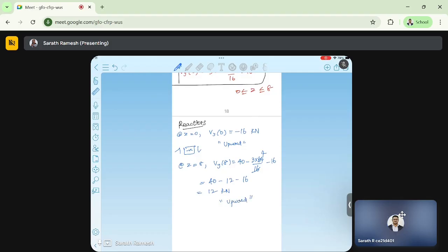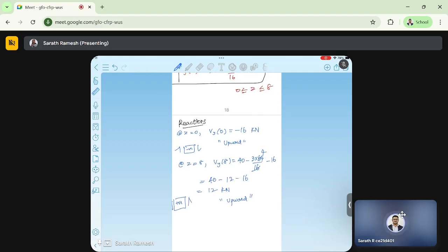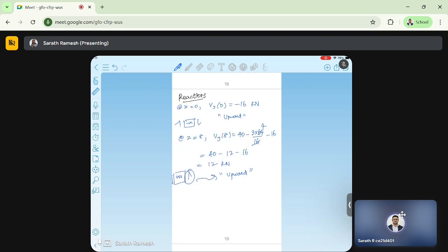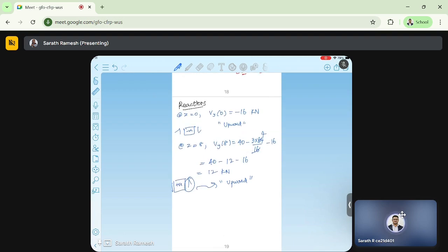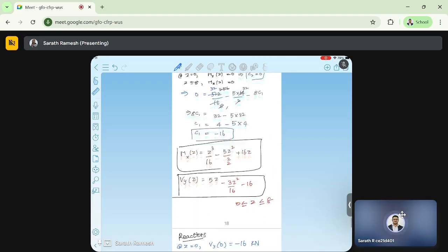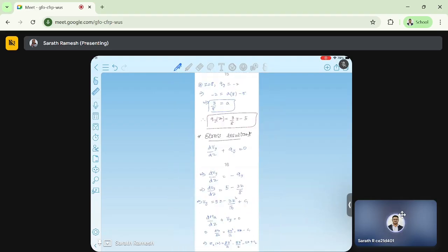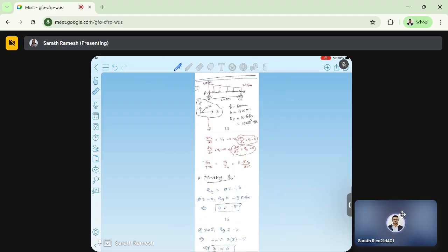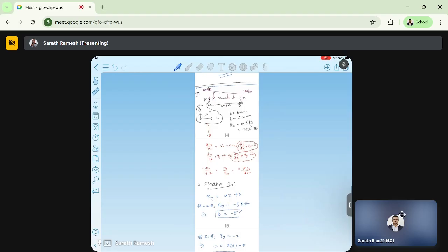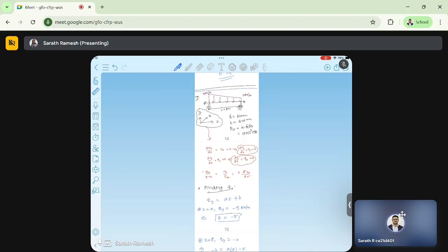Okay, my positive shear force convention is this. I am looking at a right side section at B. So this will be my direction, that is upward. Okay. So this is all about reaction, and we know moment at A and moment at B is zero. This is using equilibrium, the differential equations. The same thing actually we could have done using the free body diagram, without doing any of these differential calculations or integrations. Directly we would have got using free body.